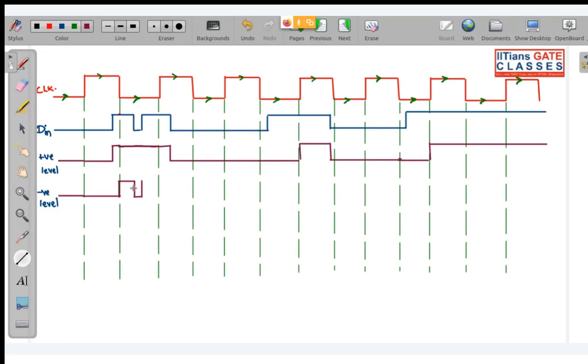Okay, so you can see what? That this transition, or whatever change in input, is happening in your D flip-flop, your negative level triggered D flip-flop. And on top of that, your D flip-flop has zero propagation delay. At the moment, I am not talking about propagation delay anywhere. Later on, we are going to study propagation delay in flip-flops. But at the moment, I am assuming that whenever there is a change in input, your output will change immediately. So you can see in this negative level, your input is being maintained at 1.